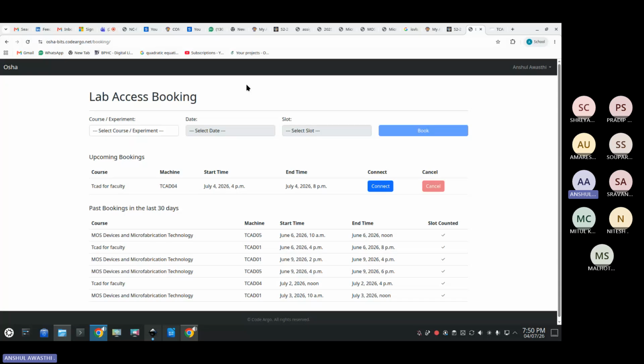You have to either write the SCM for that, or construct it in the SDE. And I'll give you certain parameters to vary. For example, I'll tell you to vary the doping concentration of drain. Just vary the 5 values of drain concentration and see the current, as I demonstrated how you can vary the doping concentration. Similarly, I will tell you to vary the VDS voltage and see the effect on the current. I can give you three parameters, and accordingly you have to plot the current.